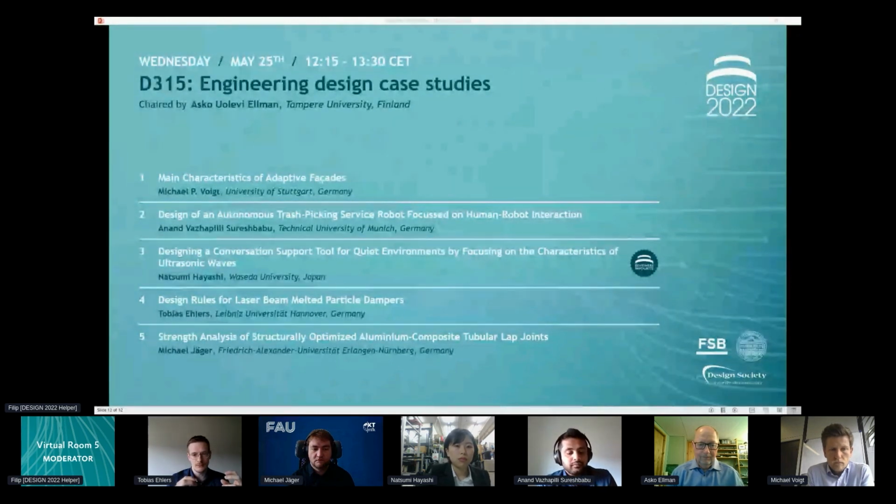And when you only want to achieve a high damping with 5% cavity volume, I think it is better to take 3 or 4 cavities and place them in the area of the highest deflection. That means for the first mode, you can put the cavity in the middle of the beam, and for the second and third mode, you can place the second and third cavity in the area where the highest deflection is. I think that is also a good solution.